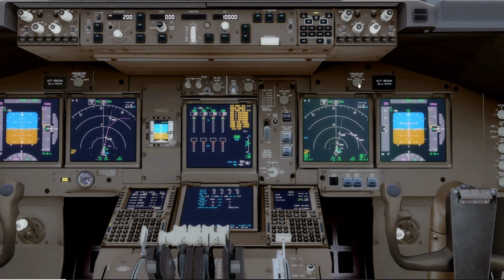MFD, inboard display is on MFD, and then the ND, ground speed 0, no flags, as desired with the VOR ADF switches. TCAS off displayed, your route is displayed, it's active in magenta, and again, range is as desired, things like that.